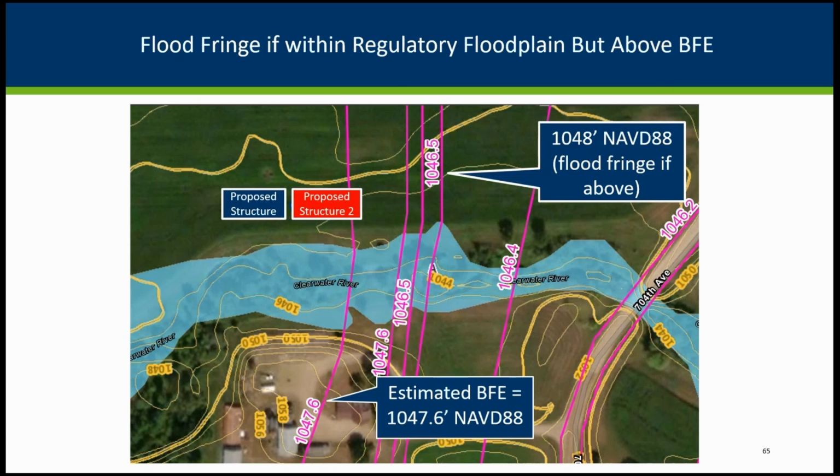However, the second site is now located inside, or maybe on top of, that 1048 contour. So some of that site is going to be inside that contour, and it becomes a lot less clear whether or not that site is above the flood elevation or might be below it. You might need to do a little bit of additional work to make sure that it is not the floodway.